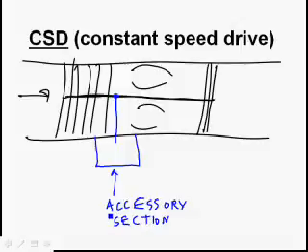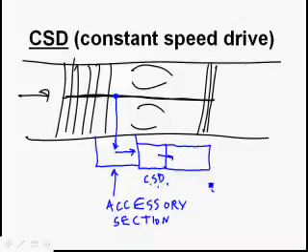There's something on the engine where you can get power out of it, not just to drive the aircraft or the car. So the power comes out and it's going to come into a shaft and it's going to drive a constant speed drive. And the constant speed drive is going to drive the AC generator.